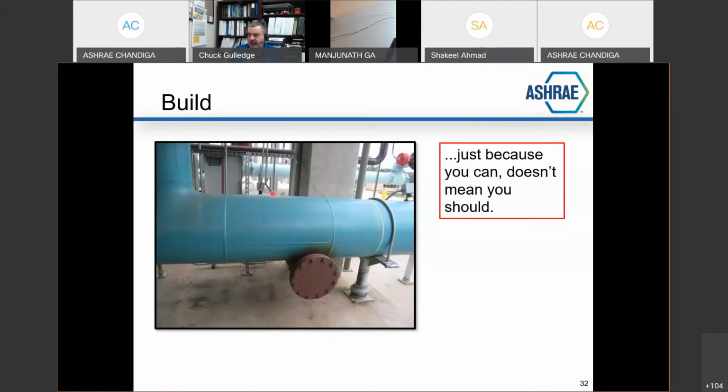It used to have side stream centrifugal separation and zero water loss component. And it was working so well that the facility manager got tired of pulling bags out and disposing of the debris like it was supposed to do, and it was keeping debris out of the cooling towers. He paid somebody to come in and rip all that out and put a sand filter in blowdown scenarios.